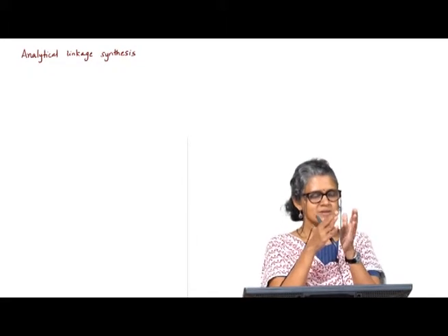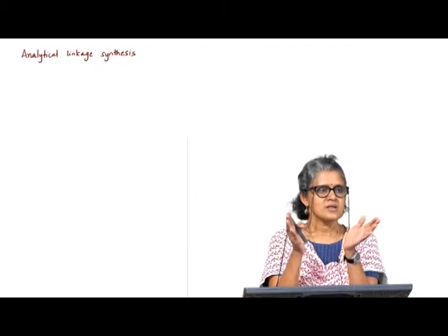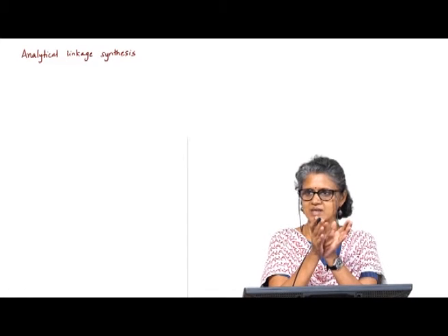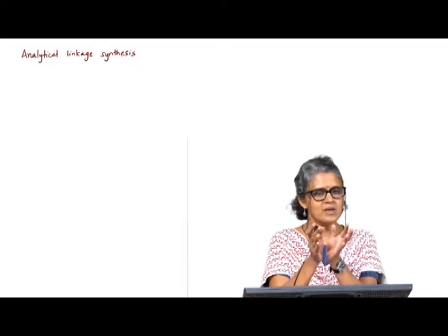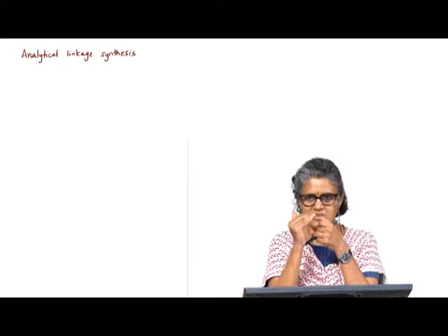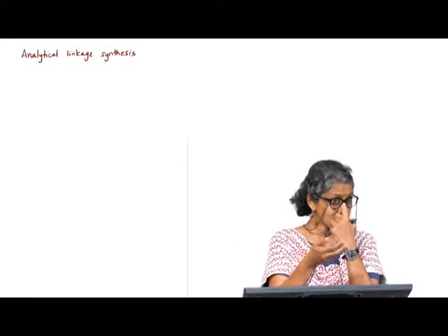You are not looking at the behavior over a range. The Chebyshev spacing applies when you want to minimize the structural error over a range, but if your application only demands that there are set positions that you want to attain, then you do not really need to go through that process.